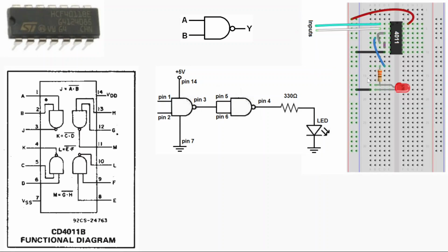So let's build this circuit. So we place the IC. As you see, we have the legs of the IC on one side of the breadboard, where the notch or the gap is, and the other legs on the other side, so that they are not connected, because we cannot place an IC on the left side of this breadboard or the right side, because they will get shorted, and that's exactly what we don't want, to avoid damaging the IC. So this notch is basically there to provide that separation, so that we can easily place components like integrated circuits or switches or anything similar on this particular breadboard.